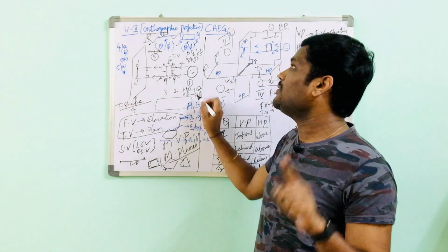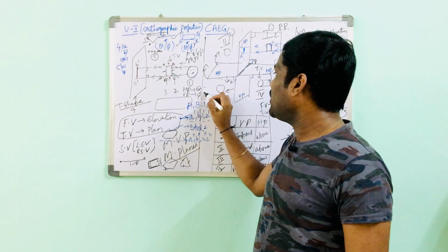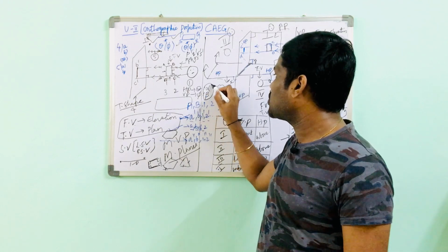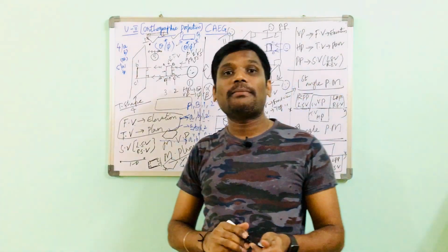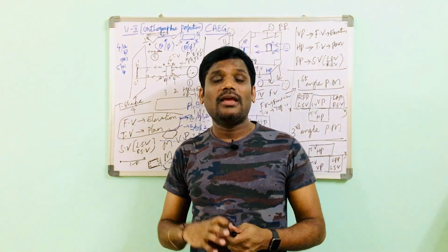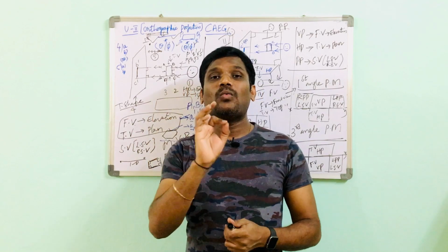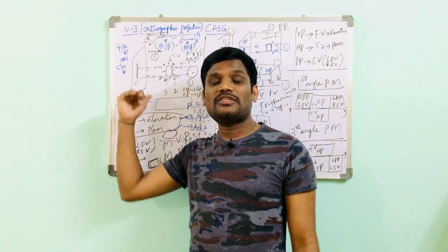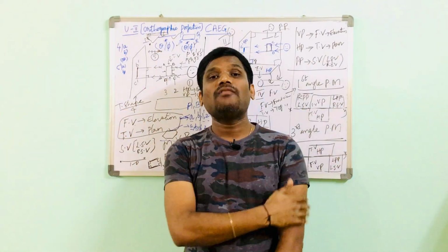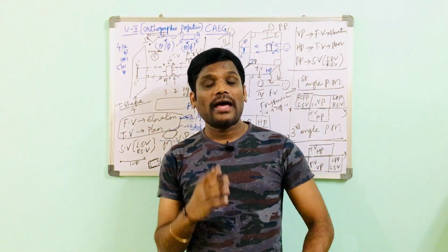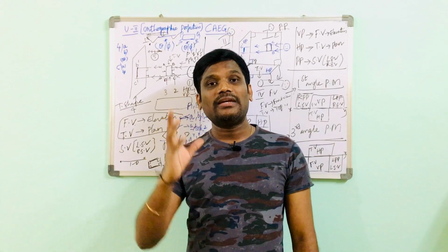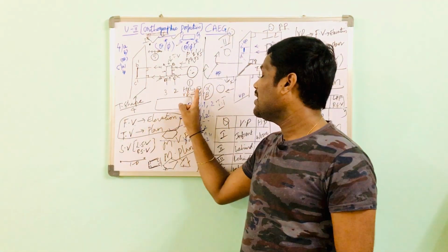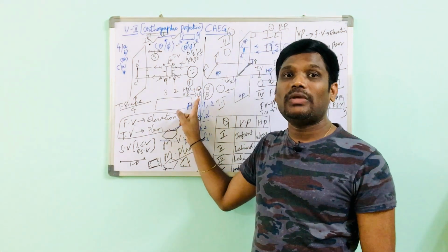But coming to the lines concept, we'll be getting two more angles, alpha and beta, coming into the picture. Alpha and beta are nothing but apparent angles. What are apparent angles? With respect to HP and VP, how do you define the apparent angles? Apparent angles are those which are greater than the given angles. Given angles are nothing but what? Inclined to HP, inclined to VP.